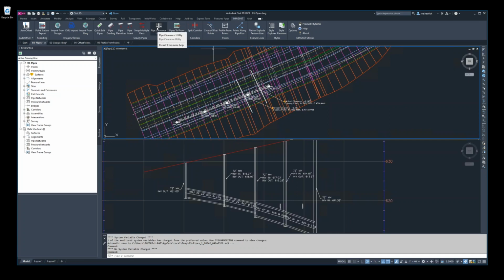And the way that these have always been meant is, they started with a request to make Civil 3D work a little more like Land Desktop did back in the day, and just to provide some, I'm going to say grading tools for pipes, but really tools to get consistent slopes across a pipe run, to be able to designate starting and ending inverts, and just let the product figure out everything in the middle. So that's what we've done.